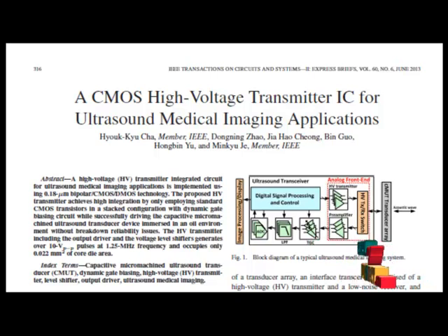For the transmitter, high voltage linear amplifiers are commonly used to drive the PZT load to achieve linearity and acceptable efficiency. In the case of a CMUT load, linear amplifiers are not optimum and decrease the overall power efficiency of the transmitter stage. High voltage pulsers can be used instead of amplifiers so that the power dissipated while charging and discharging the capacitance does not contribute to the acoustic output.